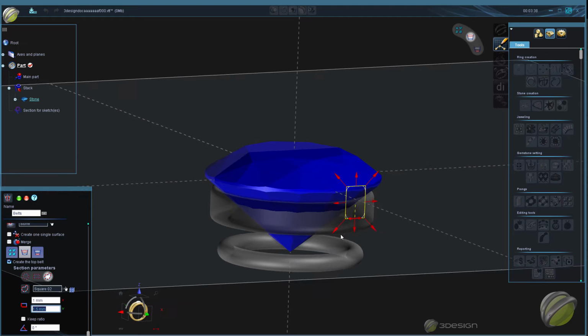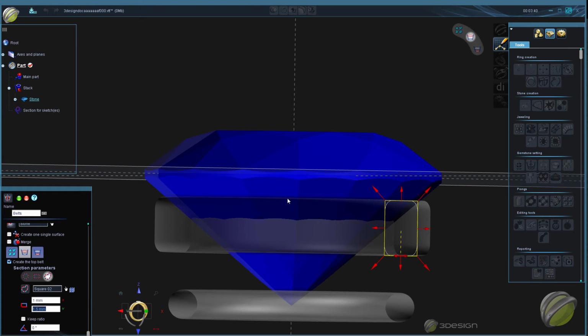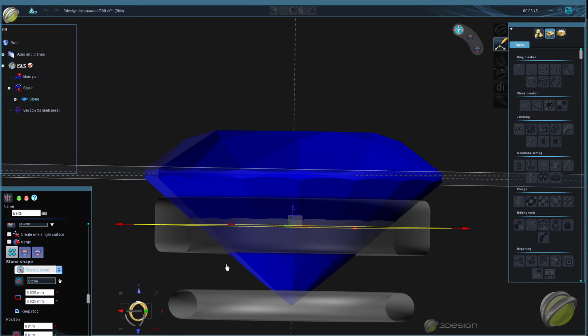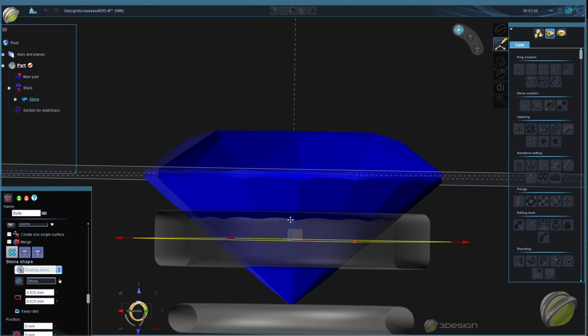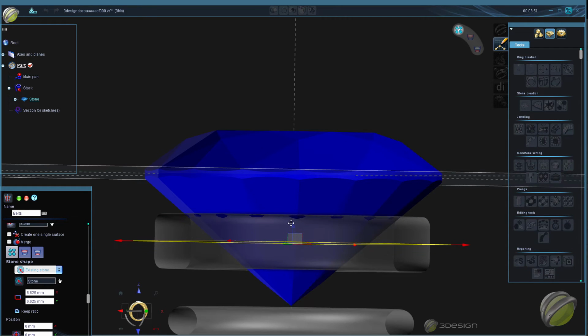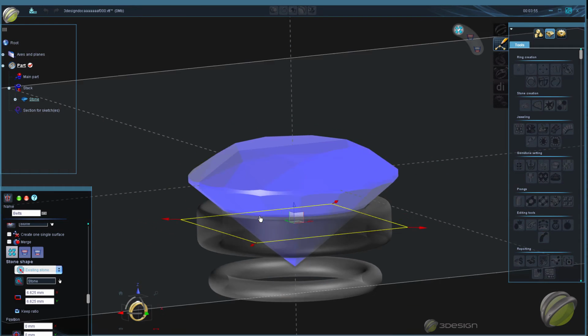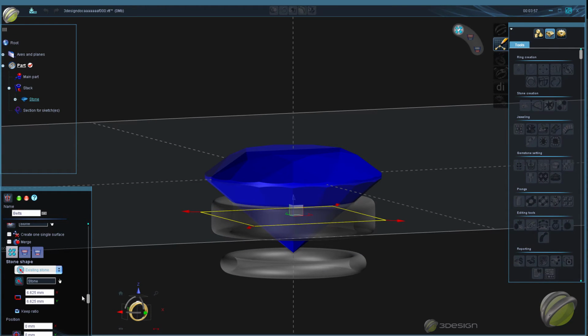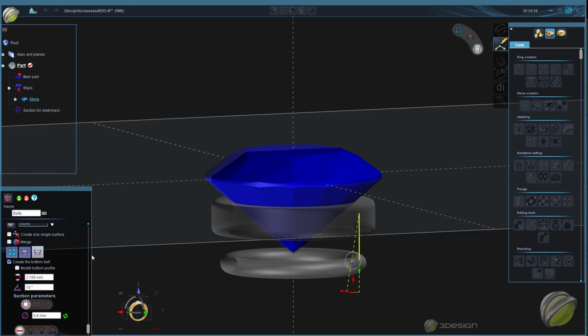And then we see now that we've resized the belt, it's sticking into the stone here. So we're going to go back to the shape tab, and we can use the transform gizmo here to now adjust the height more appropriately. And I just move it down until you see that overlap disappear. So we've got our top belt. Now the bottom belt, we can make a different shape or we can keep the same. We'll go and adjust those settings here in the 3rd tab.